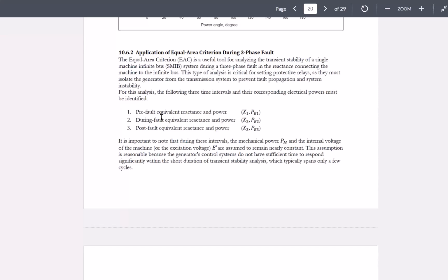See, X1 in general is representing the impedance that is existing. The smaller that impedance is, the better your system can transfer power, okay? So we always like that reactance or impedance in general to be smaller in power systems. Under ideal conditions, those impedances would be zero, right? There's no impedance in the system, for example in the transmission system. But that's not the case in reality.